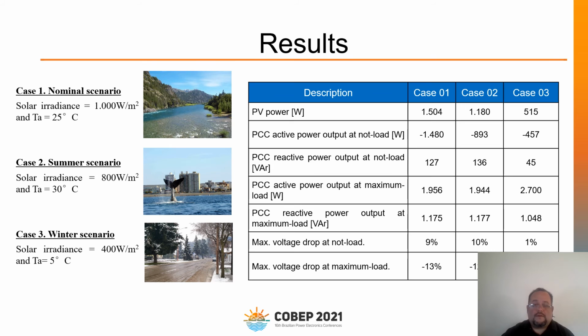In this table, we can see the results of the laboratory for each case, where the students take input and output inverter voltage and current, PV active power, point of common coupling active and reactive power to generate a report. If there is some unstable signal, it was described in the report.